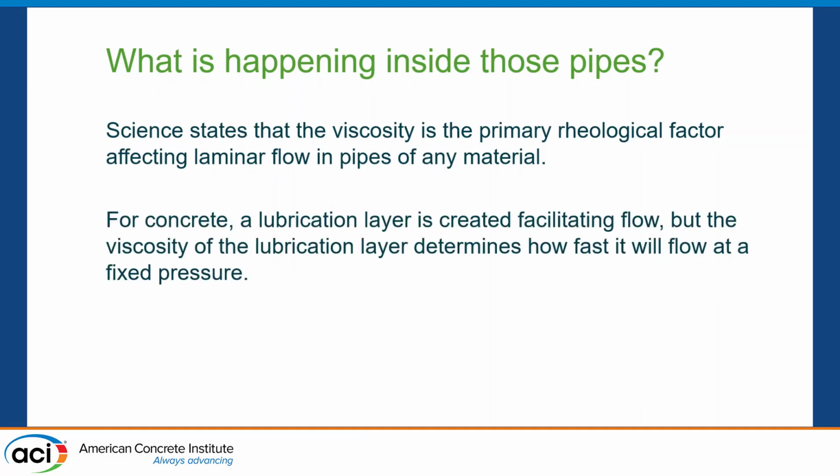So for concrete, you get that lubrication layer being formed, it facilitates flow, and pressures go down by about a factor of 5 to a factor of 10 compared to not having a lubrication layer. And even if it goes completely to friction, then it's a totally different story.